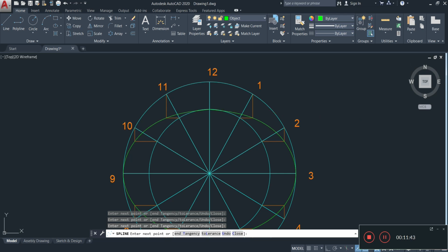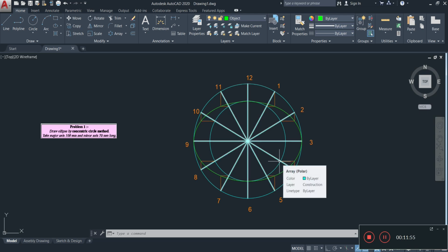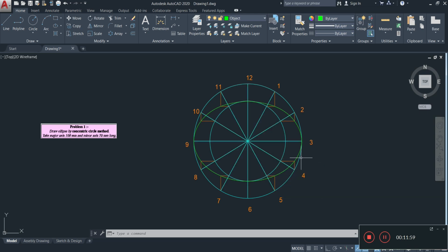If you press escape, you will exit the command and will have to redraw your spline. Alright, so once that is done, this is your ellipse. Your ellipse is now complete. The only thing that is missing is the title and possibly dimension. So if this is an SBA piece, those are what you need to add. I'm going to be adding them now so you can follow along.